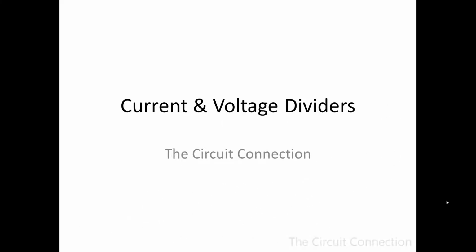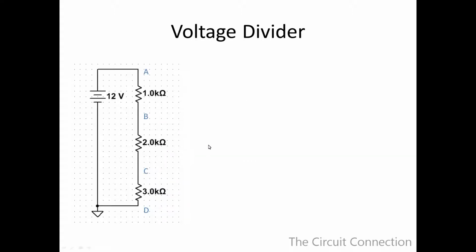Hello everyone. In this video I'll be talking with you about current and voltage dividers. There'll be some very basic ones, but sometimes you have a situation where you have 3 resistors instead of 2 that you want to know a voltage divider rule with those resistors. So I'll be deriving that in this slide presentation here.